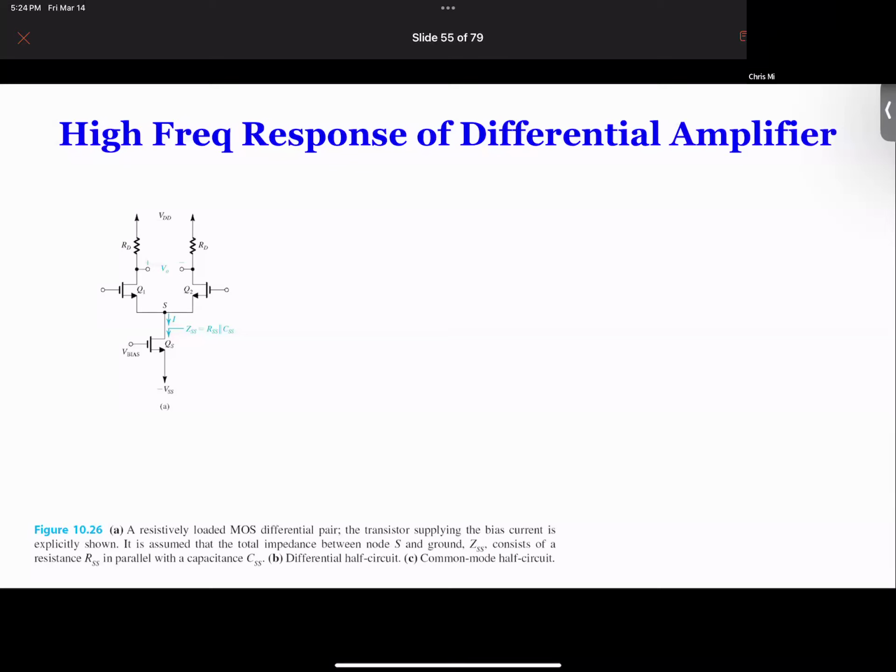really the difference is here, if we break this down into two separate circuits, what do you have? What you have is a common source amplifier. And for the common source amplifier, the top is the same. But the only problem is at the bottom, instead of a ground, we now have this resistance, and this one also has this CGD, CGS. It has its capacitance too. Now, ideally, we should probably consider that capacitance as well. But the impact of those capacitances is relatively minor to the actual gain. So in fact, we will neglect it.